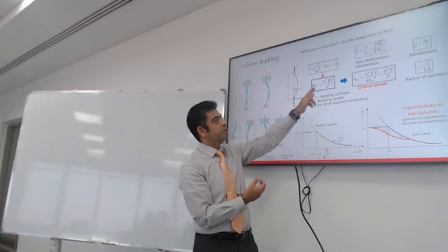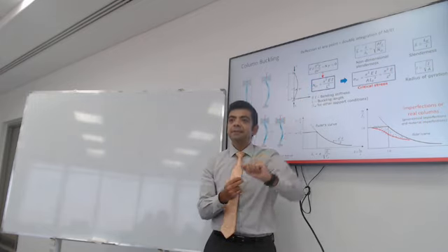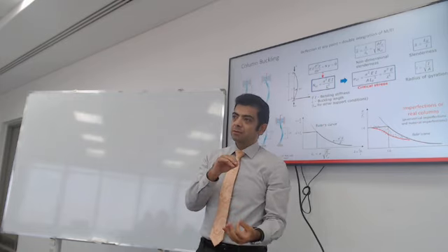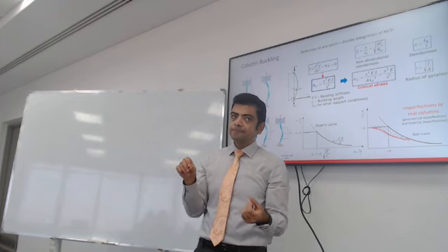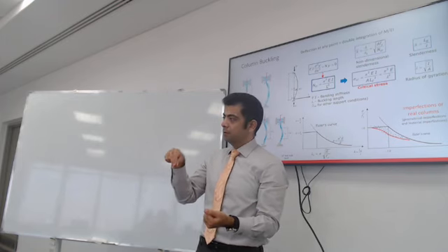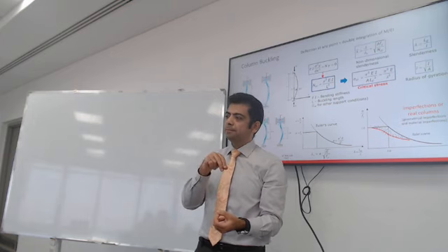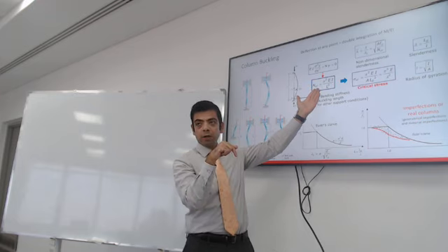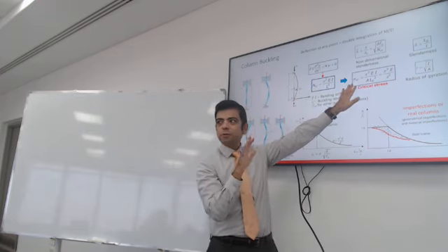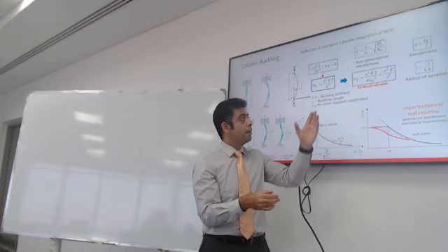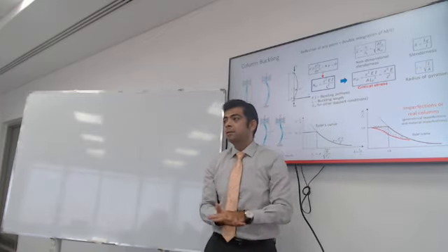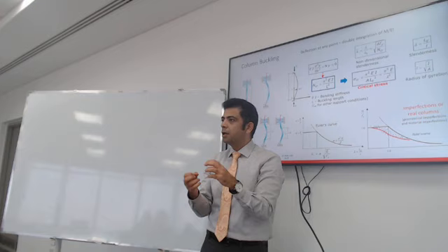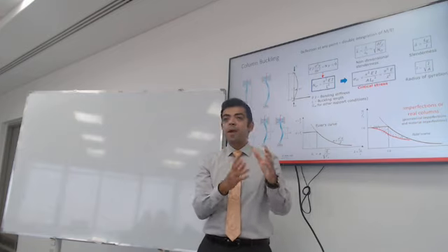So what is the difference between the critical load and the critical stress? What is the difference between load and stress? Force and stress. Force is in kilonewton. Stress is force divided by area. So if you divide the critical force by an area, it gives you the critical stress. If your column is stressed more than this number, it will buckle. So it kind of takes the shape out of the equation. It's going to divide by the area, so you can calculate the stress and compare it to the critical stress.